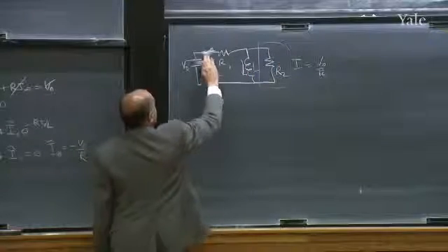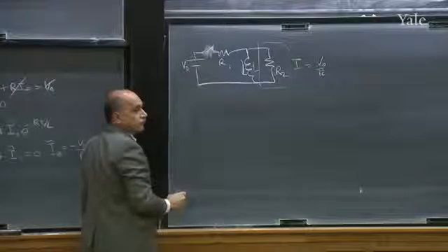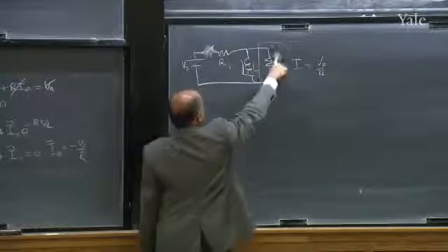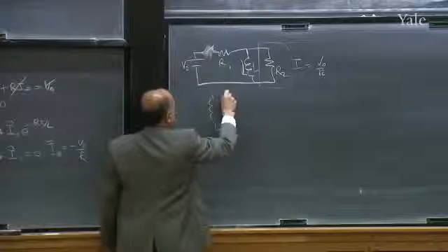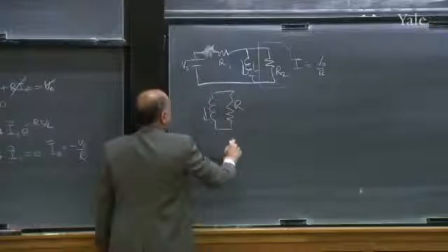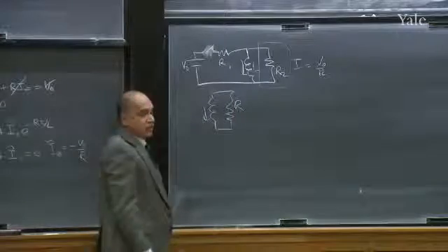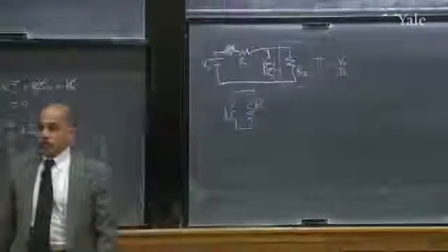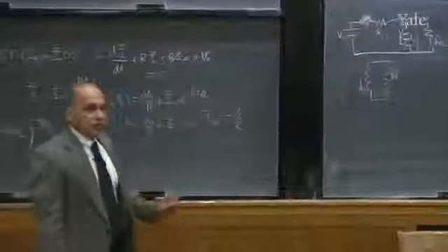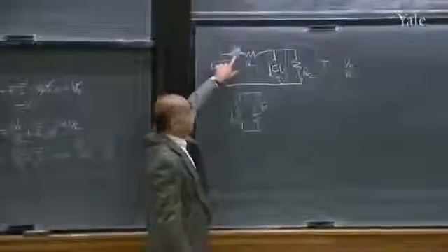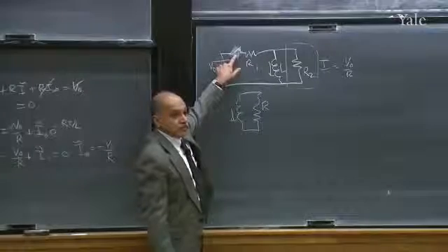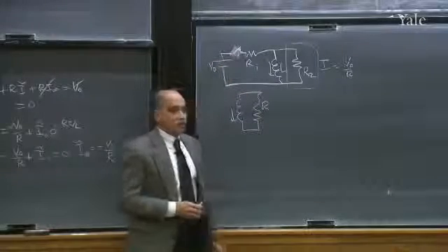But now if you throw this switch open, you have given it a path to discharge. So the inductor will discharge through the resistor. The current will continue to flow in this direction. Of course, it cannot flow forever because the resistor will burn up the energy. But you're giving it a path. You're avoiding, in a way, if you like, this is also a path with very, very high resistance. The air is a path with very high resistance.